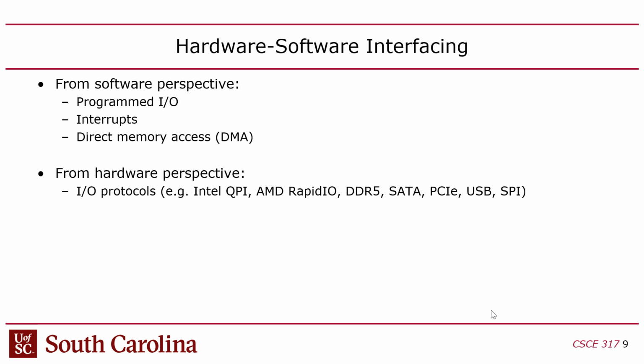The problem is, what if the hardware, the peripheral, wants to do something? It wants the CPU to service it, as opposed to it servicing the CPU. What if you have a peripheral that demands the CPU's attention? That's done through an interrupt. An interrupt is only initiated by a peripheral, by a hardware component, and it's basically a wire that goes back to the CPU that tells the CPU that someone needs its attention. The CPU can ignore it if it wants, or if it wants to service that interrupt, it can do so, at which point it has to then use programmed I/O to say, what's up?